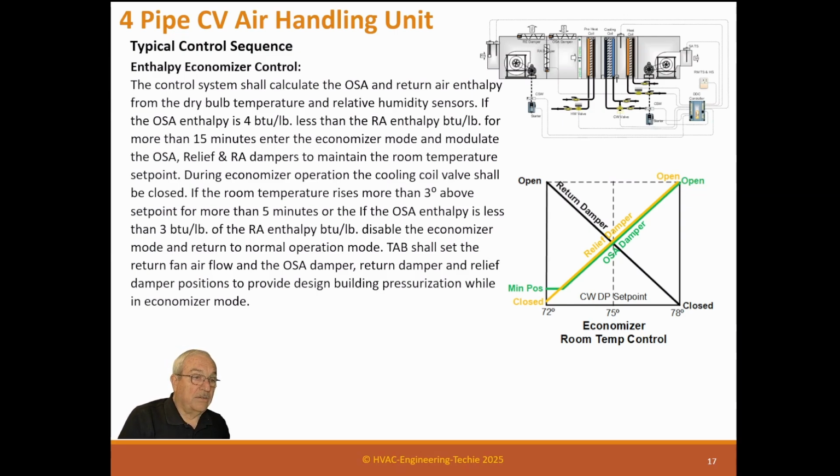So the outside air is a little too warm, and the cooling coil is dropping it down. And you don't want to do that because now you're double dipping. So what I like to do is, if you're in economizer, let's use economizer. When it's right at that shoulder load, let's just turn it off. There's too big a chance of wasting energy. Let's just turn it off and go back to air conditioning, because remember, the central plant is really, really efficient when it's that cool outside. So you're getting really high efficiency anyway.